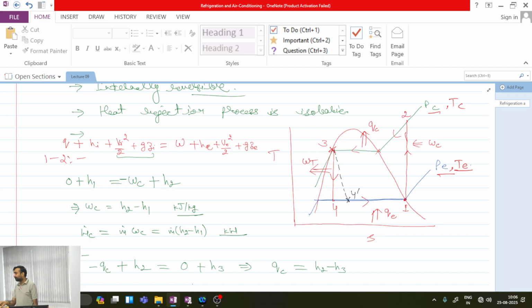Now of course, it's very clear that if we have to decrease the pressure, we have to provide some restriction to the flow. What we can do is, in front of a bigger tube, place a very small diameter capillary tube. Whenever flow happens through that, the pressure drop across the capillary tube will be large, so it decreases the pressure between its two ends. Similarly, if you take a valve and make a very small orifice in it, then also what will be happening?